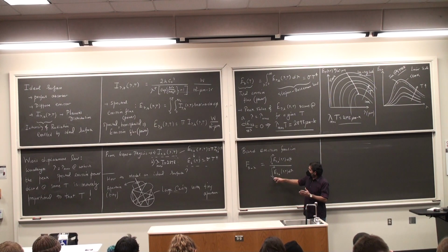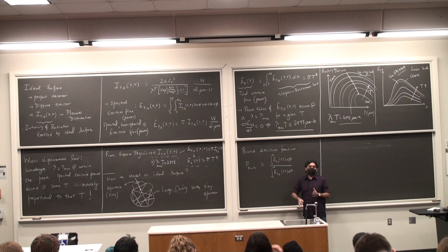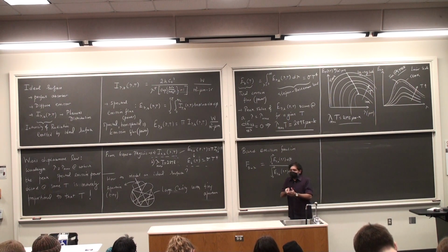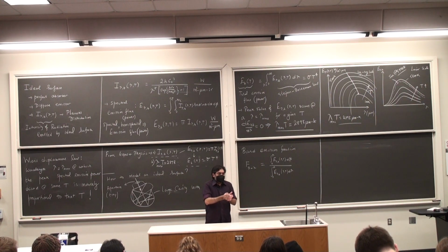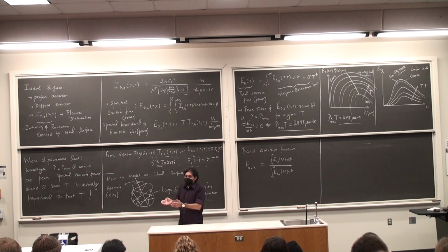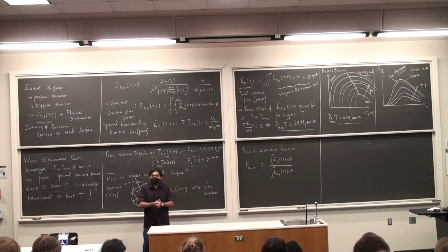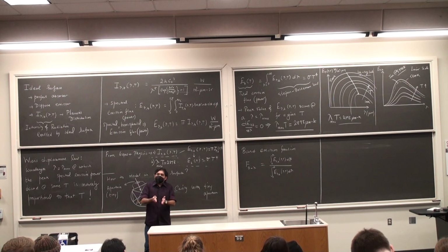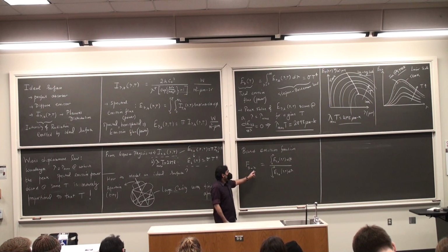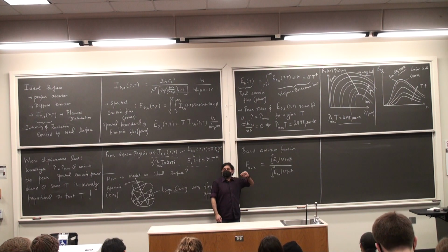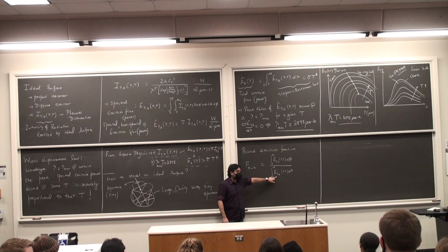That is, I am not interested in things happening between 0 and infinity. Who cares? Most of the time I am interested in radiant energy between a certain wavelength range, maybe from 0 to lambda or lambda 1 to lambda 2, where I could define the limits of lambda 1 and lambda 2. So why am I calculating it from 0 to infinity all the time? Let me pre-record all of these fractions, which I can very well do because I know this guy.